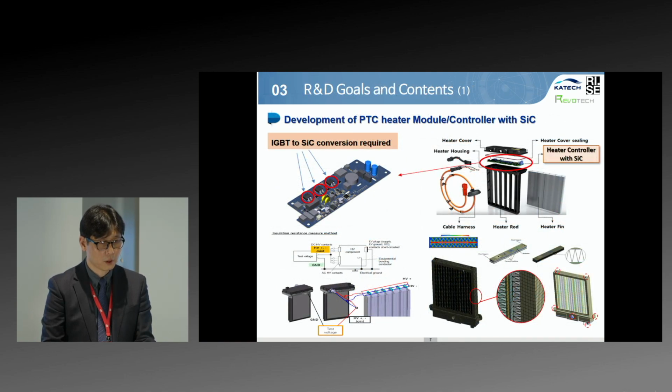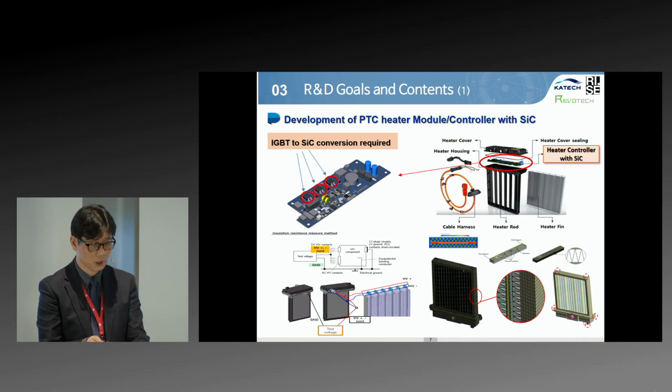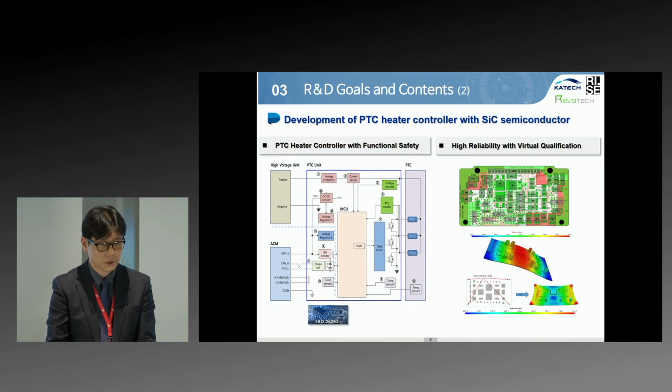This slide shows development of PTC heater module and controller with silicon carbide. The replacement from IGBT to silicon carbide is required. It is expected that one silicon carbide MOSFET corresponds to 3 silicon IGBTs. The PTC controller will be developed with functional safety technology as well as virtual qualification technology applied. Virtual qualification technology is a reliability simulation technology using the influence of temperature and vibration in harsh environment conditions.